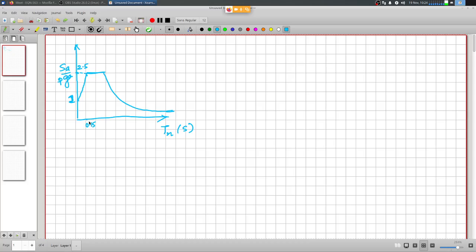So if the error in estimation of natural period is because of the modeling considerations rather than the actual behavior, then you might actually incur much larger force than what is implied by this linear arm of the design spectrum. So in order to protect against that possibility of underestimating the forces, you have this flat curve for the design spectrum.